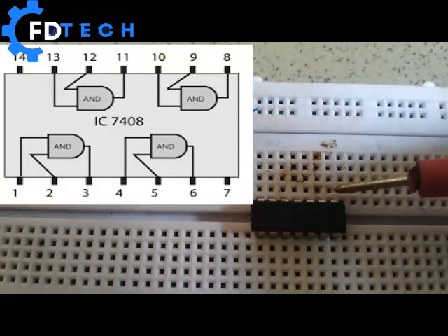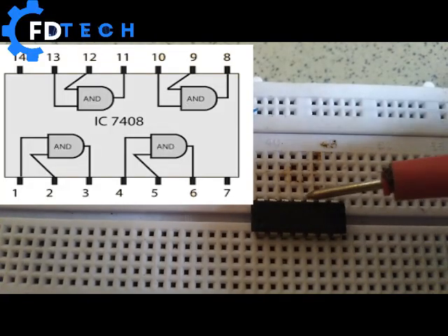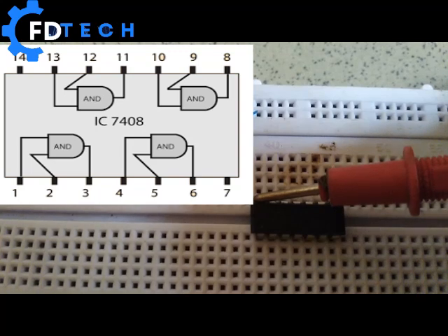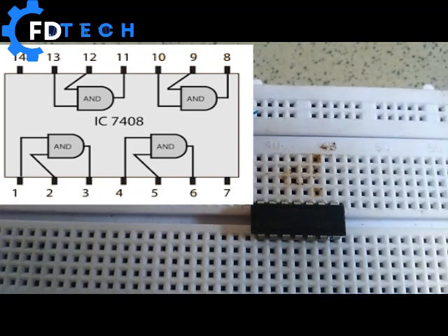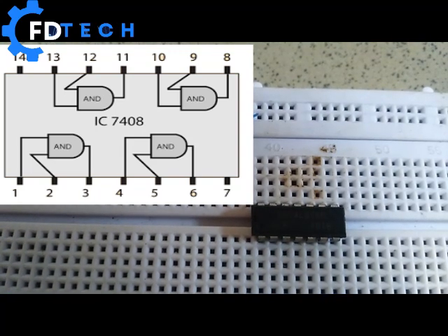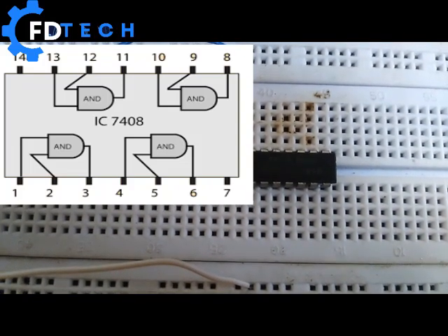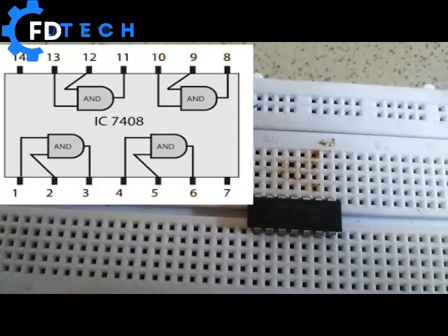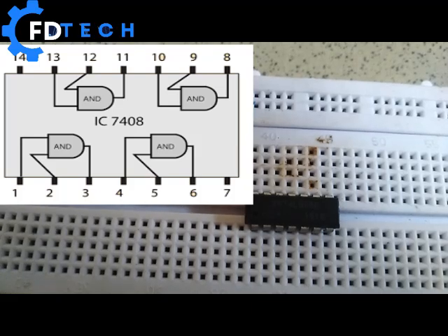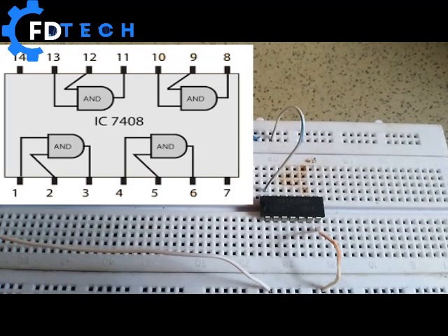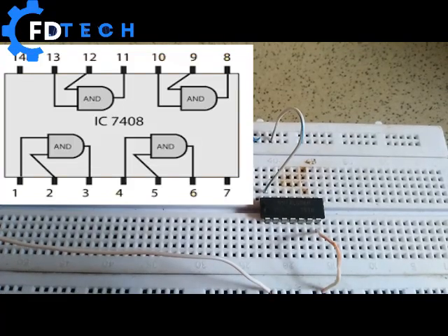And going over, you have pin 8, pin 9, pin 10, pin 11, pin 12, pin 13 and the last one, which is pin 14. Now what I do next is to connect my pin 7 to the ground area, just as I did for my battery, and connect my pin 14 to the VCC. Looking at it very well, it is well connected using my jumper wires.